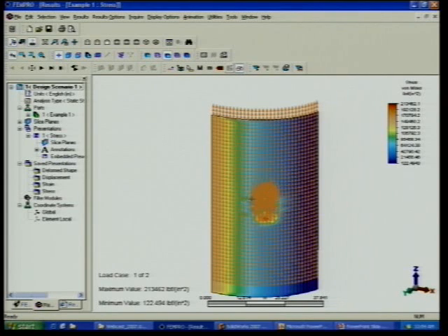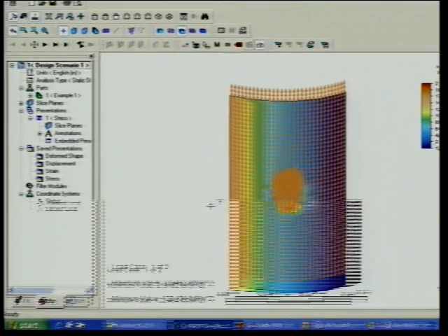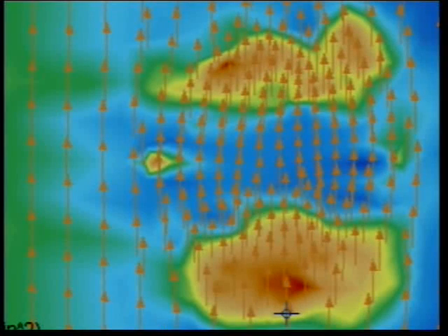And if you zoom in to that refined area, can we see that? It's very hard to tell. But what I wanted to show you is that regardless of how the elements themselves are oriented, the axis is always pointing in the z direction. Okay, here we go. All these elements here, if you remember, they're not fully rectangular with all parallel lines. They're not, but you can see that the axis is always in the z direction. That's because we specified that vector in the element definition.